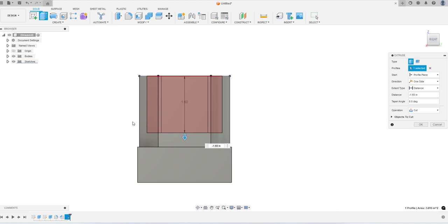You'll notice maybe that this extrusion for the outside area was 2 inches. You can actually change that a little bit. What's important is that we have a 1/2 inch clamping boss, which I'm going to show later on, that's not moved. So if you wanted to have a taller lid and a shorter base, you could do that. It's really up to you, as long as there's a 1/2 inch in between them. The stock itself is going to be 3 inches tall, and so you'd only have so much to work with.